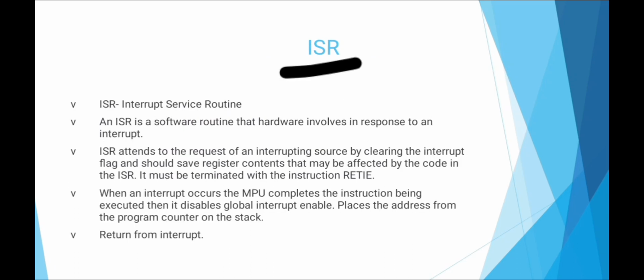Next one is ISR. ISR stands for Interrupt Service Routine. It is a software routine that hardware invokes in response to an interrupt. ISR attends to the request of an interrupting source by clearing the interrupt flag and should save register contents that may be affected by the code in the ISR.